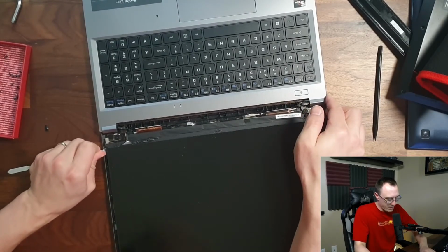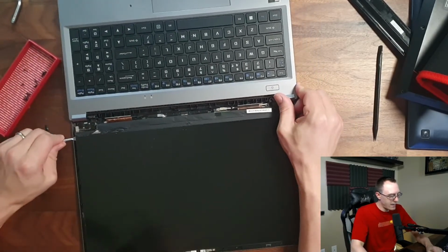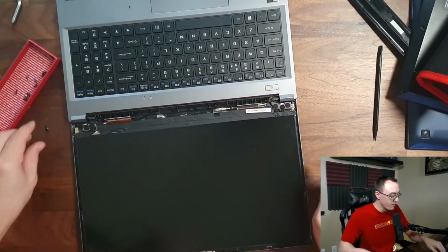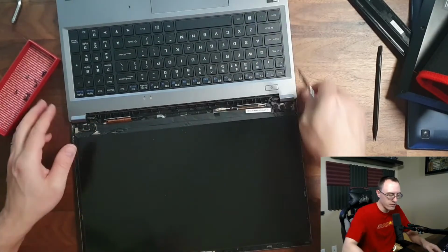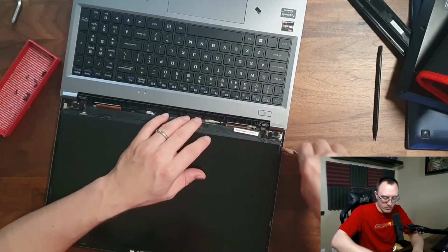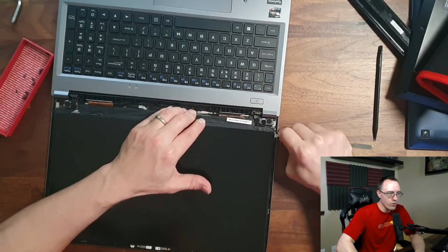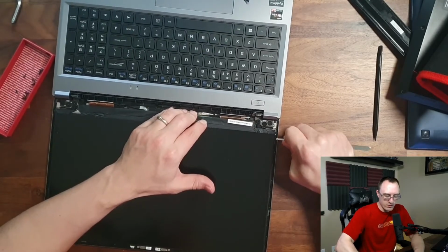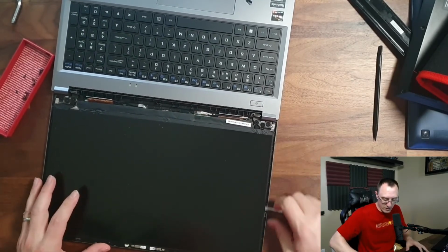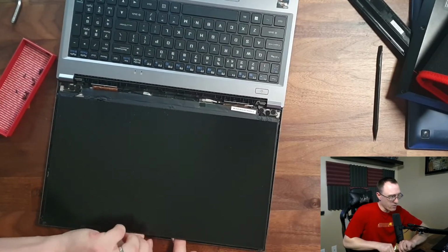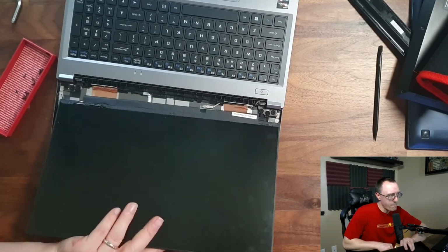So if this can just pop up though. Also, knowing is half the battle. So knowing that I'm only dealing with a really small adhesive strip, that helps a ton. We have the final adhesive strip over here, just applying gentle force. And at this point, we do not have a single crack, and the LCD is loose. Except it kind of re-adhered at the bottom left here. There we go.